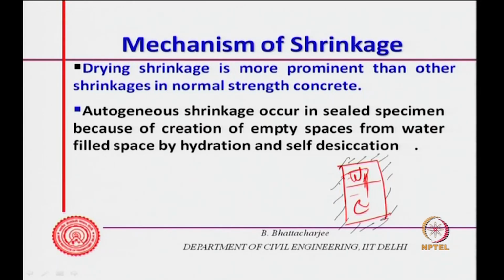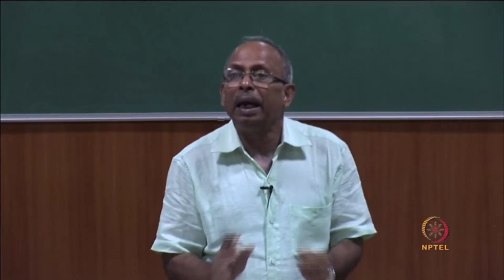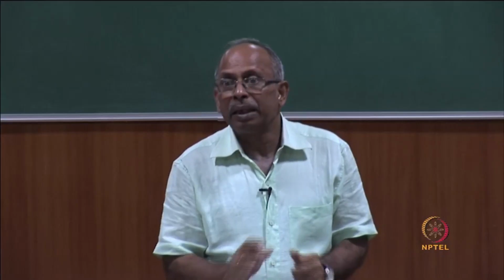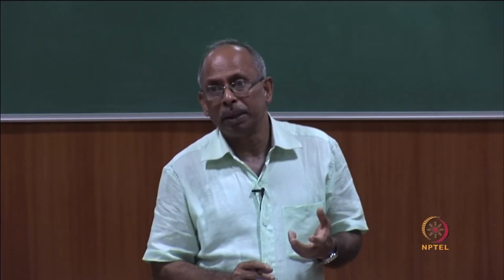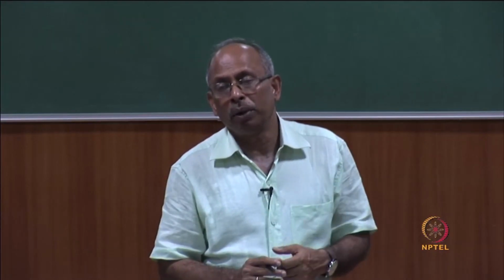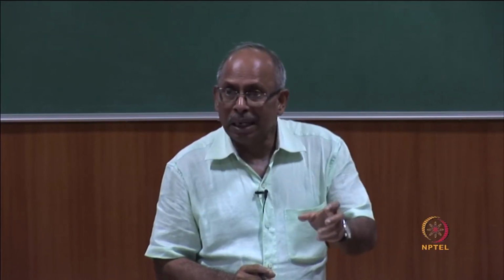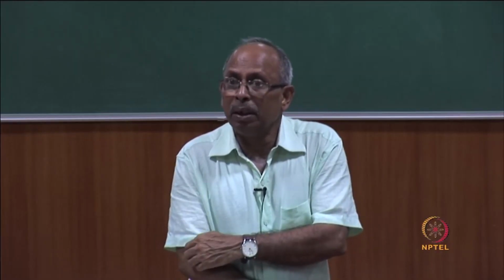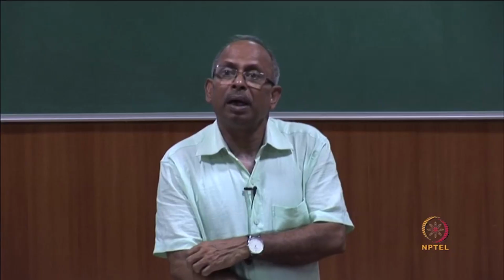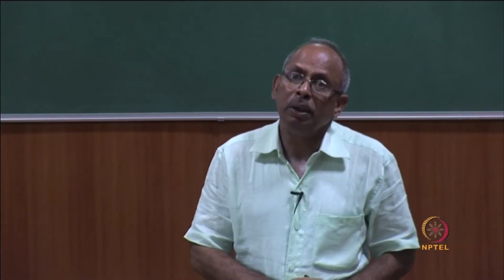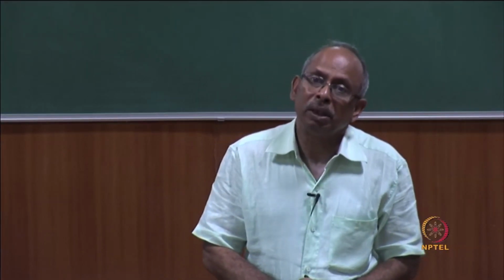There will be water loss after the skeleton has been formed, after initial set has occurred. So, empty space remains even in a sealed specimen, because the water has got lost. Whatever water was there in the sealed specimen is still remaining, besides that some empty pores are created, and these spaces are actually thought to be causing self desiccation.